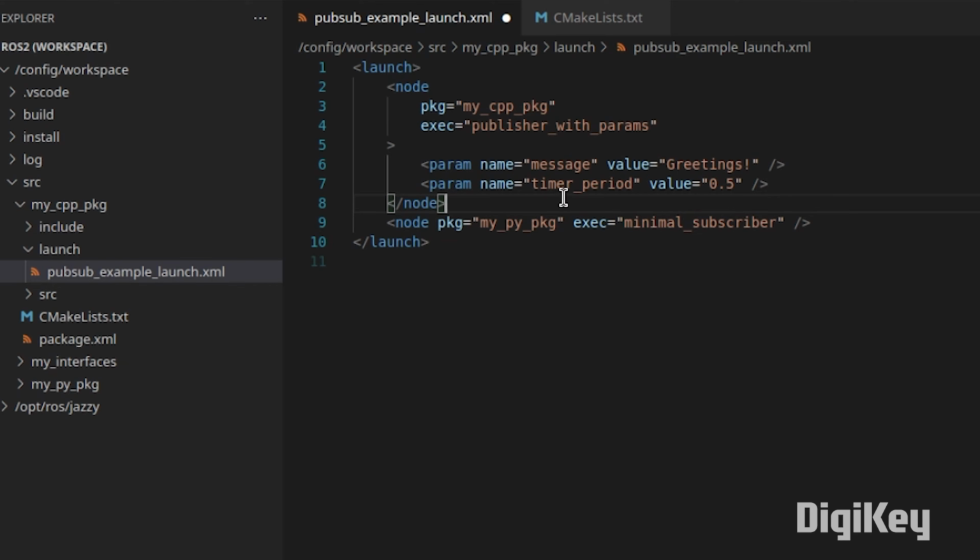I want to talk about namespaces. When you start having dozens of nodes, and you might have multiple publisher nodes or multiple subscriber nodes, especially as you get to topics that have the same name and you want to keep them separate among your different groups, you can use something called namespaces. This is just like namespaces in something like C++. If you remember, we have my topic that started with the slash, and that is the root of that topic name. When we introduce a namespace, that then extends to the root and then my namespace slash topic. So we can group our topics and our node names together under these namespaces. So let's see how that works.